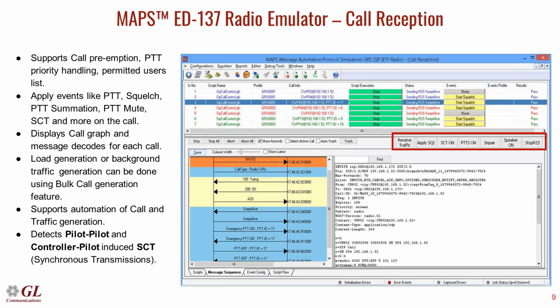Whenever the squelch bit is set and the ACT bit is set, but the PTT bit is not set, it indicates that multiple aircraft are doing the squelch simultaneously. In case of controller or pilot induced ACT, the PTT bit is also set, squelch is also set, and the ACT bit is also set. This scenario happens whenever the receiver catches the adjacent transmitter's voice and sets the squelch, when the PTT activation is also indicated by this radio.